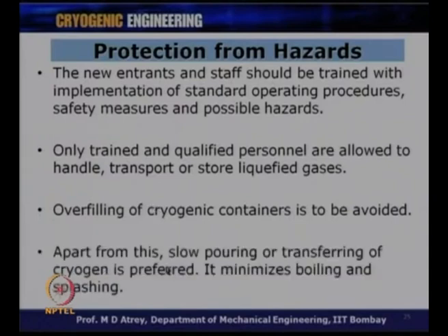Apart from this, slow pouring or transferring of cryogen is preferred. So, always slow pouring or transferring. You should not transfer liquid nitrogen very fast. It will result in a lot of evaporation of these gases, of the cryogens. We should have a very slow procedure so that fast evaporation or fast pressure build up will not happen over there. It minimizes boiling and splashing.